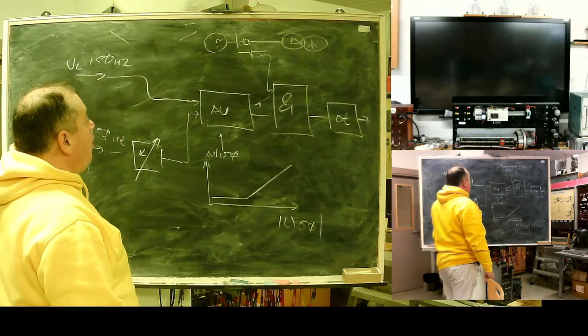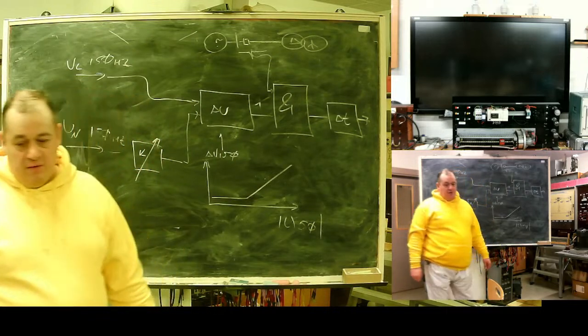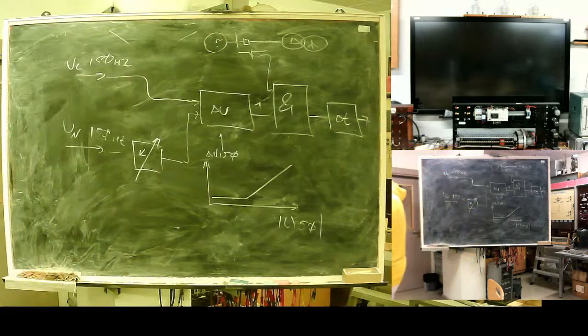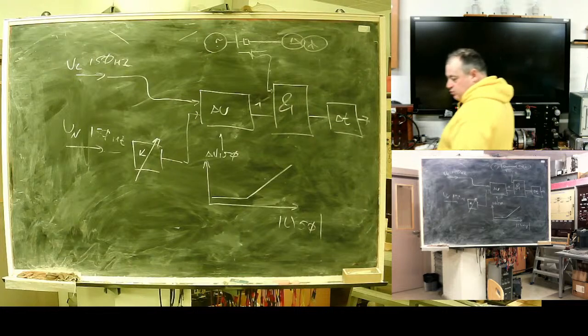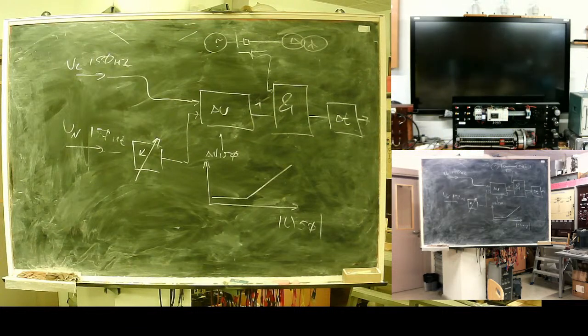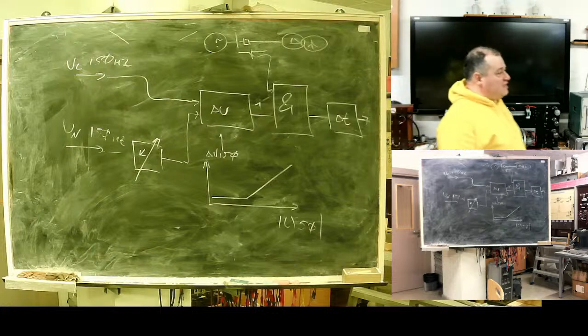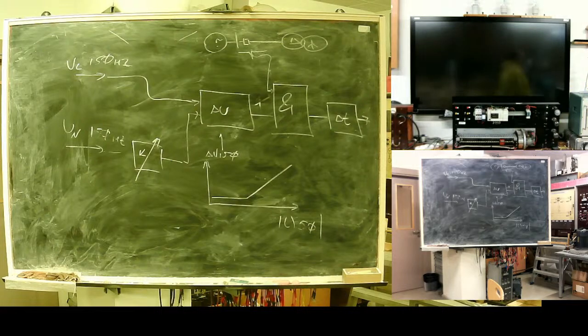And that's not all. The problem is, mostly for hydro generators, they can operate in quite a wide range of frequency, and remaining residual magnetization of the generator rotor can produce some voltage at some frequency.